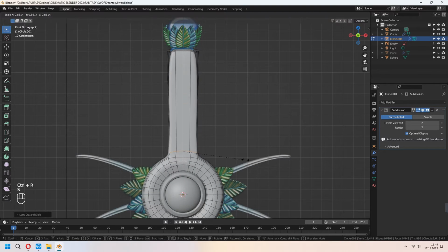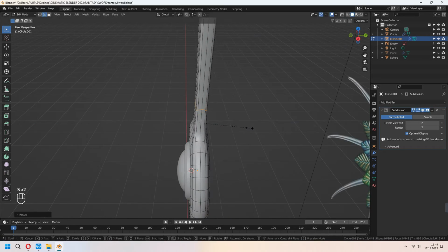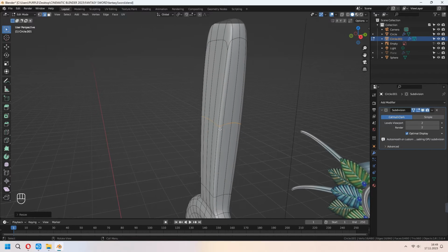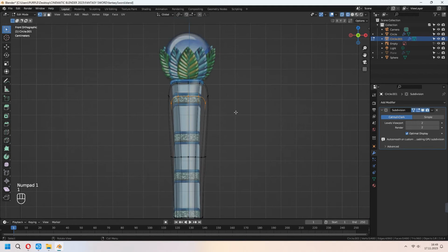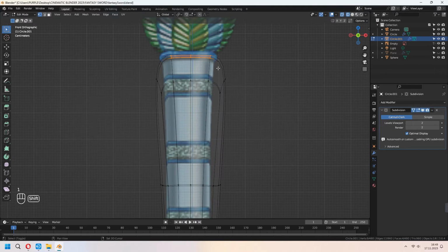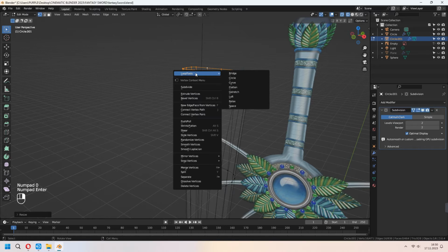But it looks a bit flat, so we have to make it circular. In edit mode, you choose your edge line, right click, and choose loop to circle. For the top parts, you can delete your vertices in here and choose the edge line as Z at 0, scale in the z-axis to 0, and right click, as you see, loop to circle.